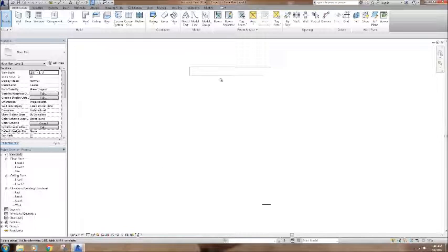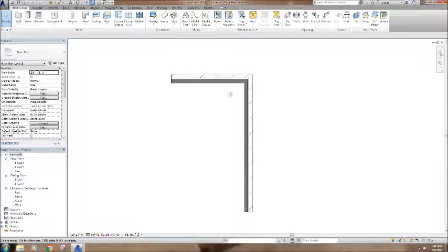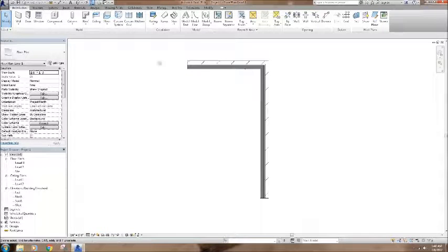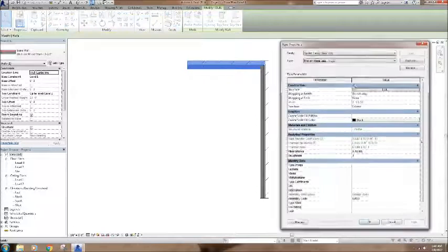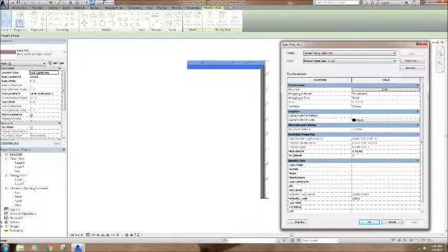Okay, I'm going to change this back to fine so we can see what the detail level is doing here. So that's, in a nutshell, how you build the structural layers of this. Now, these wrapping at ends and wrapping at inserts. Right now, when I just terminate a wall here, I get just a chopped end. So what this is showing is you're going to end up seeing the studs and all the ends of the layers just truncated there. So at the ends, we have wrapping as none.